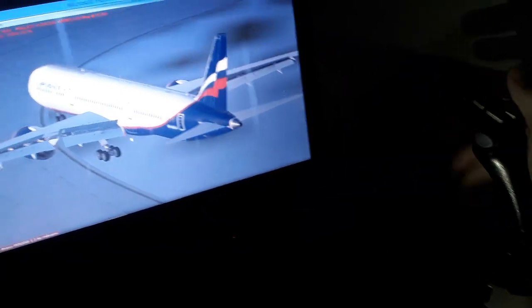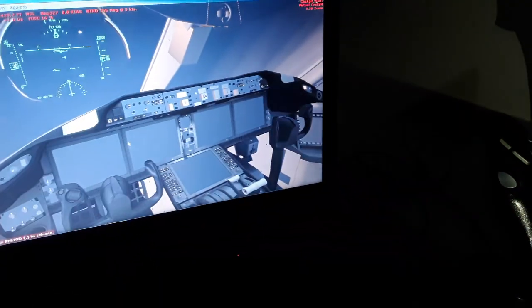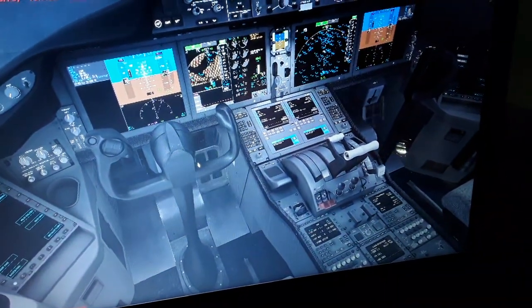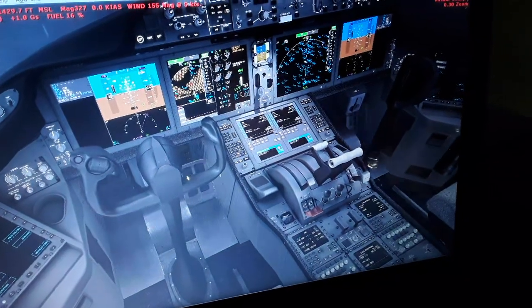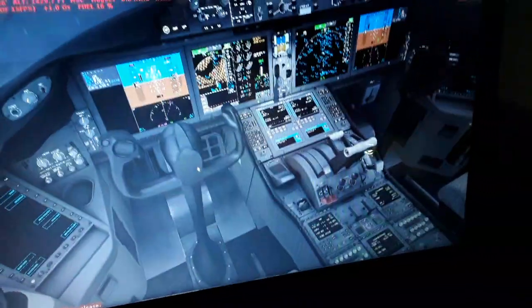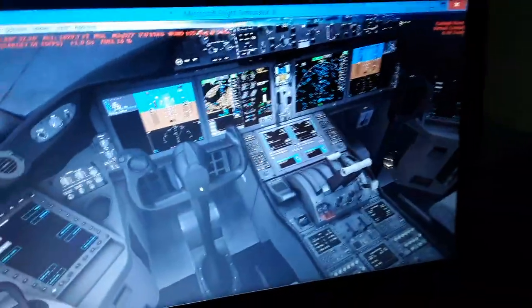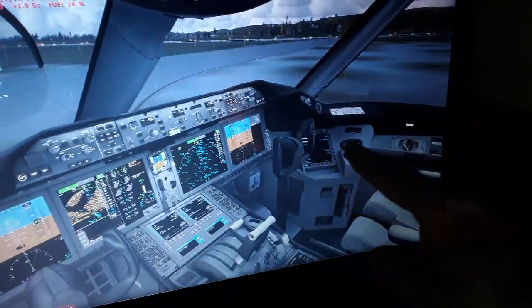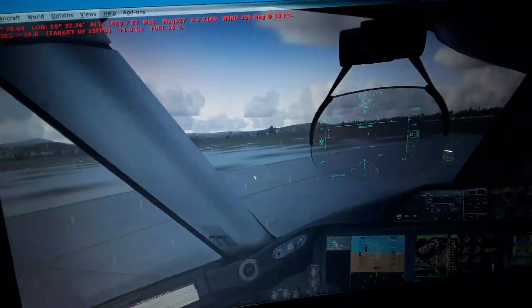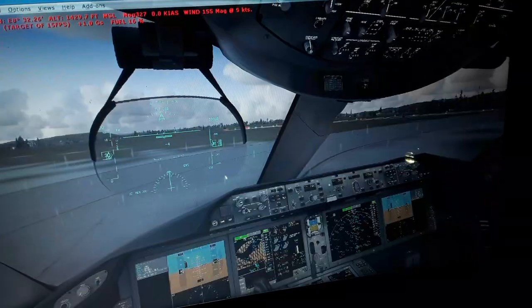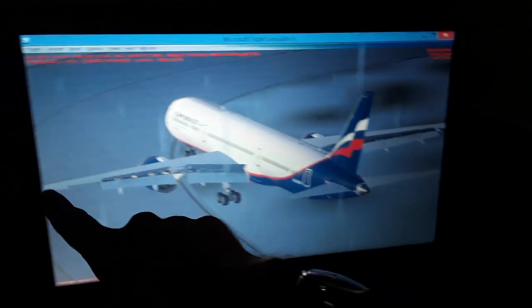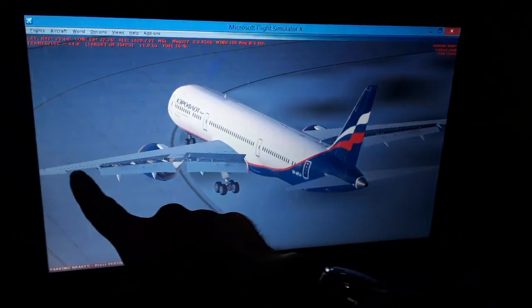From the rudder pedals, I have in the side stick the rudder pedals, so you can see the rudder pedals again. Here we control left and right nose wheel steering and the vertical stabilizer control. Also we have the toe brakes. We can apply the toe brakes when we press the top surface. For the nose wheel we also have the tiller here on the left and the right side over here.